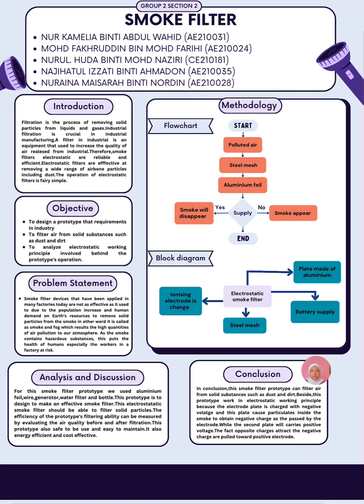Okay, for the conclusion. In conclusion, this smoke filter prototype can filter air from solid substances such as dust and dirt. Besides, this prototype works on the electrostatic working principle because the electrode plate is charged with negative voltage and this plate causes particulates inside the smoke to obtain negative charge as they pass by the electrode, while the second plate carries the positive voltage. The fact is opposite charges attract, so the negative charge is pulled toward the positive electrode.